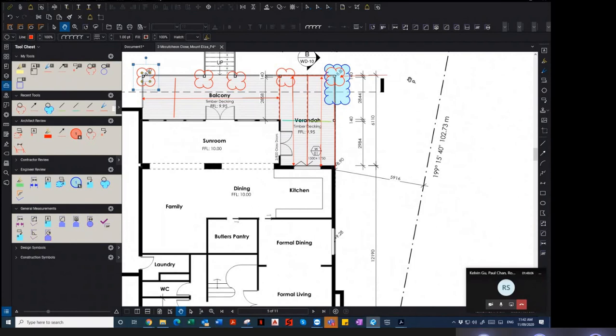So your force of 1.27 or 1.5 is divided by 5 posts. So it's a different situation to what you have. Does it make sense? Yeah. And deflection is only 5.1 in this case. It's nothing, isn't it?